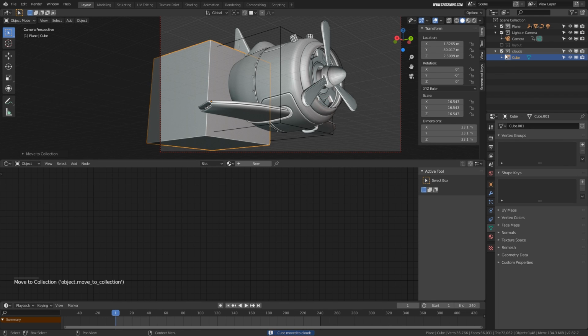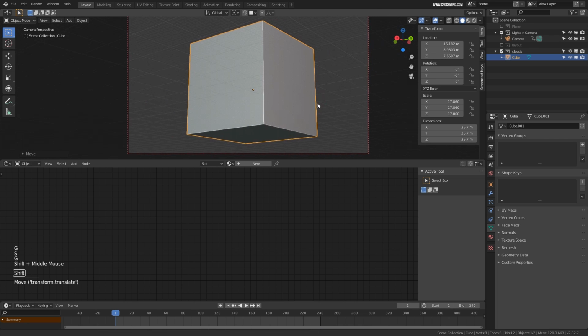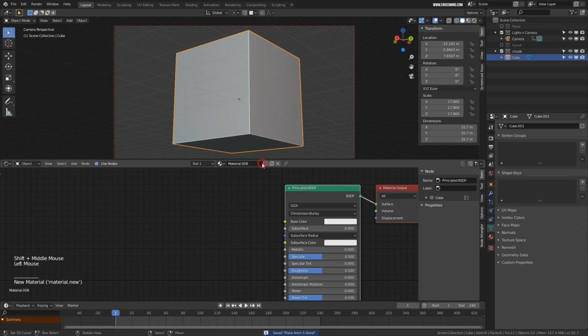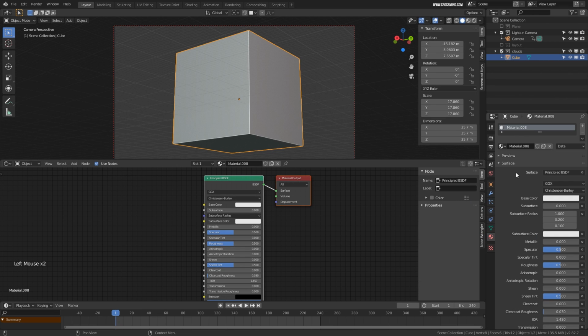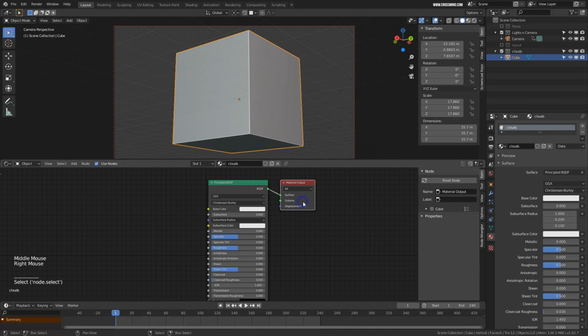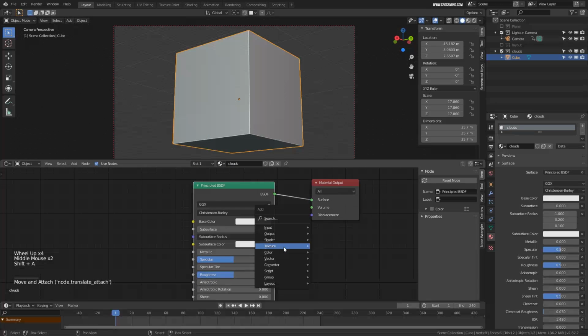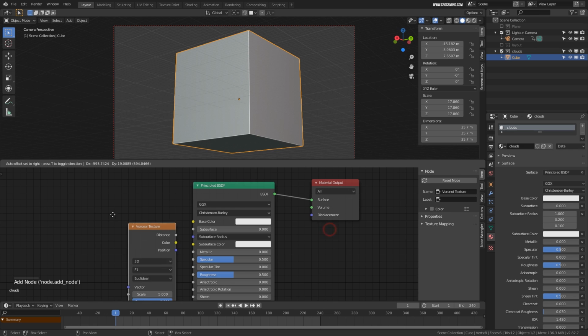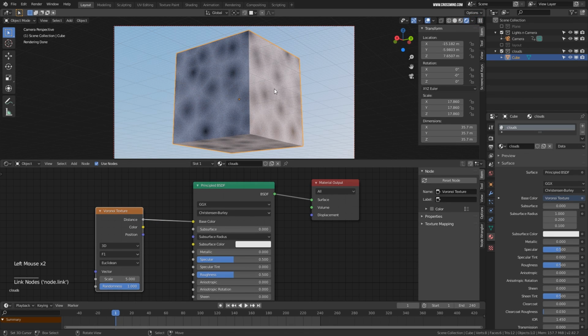Now let's disable the plane so that we can only focus on the cloud. Now let's create one new shader called Principled BSDF. It will bring Principled BSDF by default. I'll change this to clouds. So far, whatever materials we have used were surface materials, like whatever color or texture I bring in, these are always applied at the surface level, on the polygons. I can't see what is inside the object.